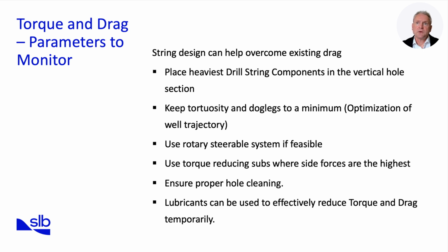Fifth, ensuring proper hole cleaning is fundamental. Even the best designed string cannot overcome excessive cuttings beds. Finally, adding lubricants provides temporary reductions in friction, useful in casing runs or extended horizontals. While not permanent solutions, they can extend operational reach and reduce stuck pipe risk when carefully applied.